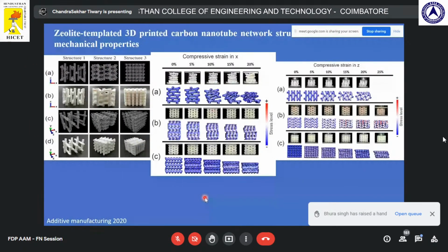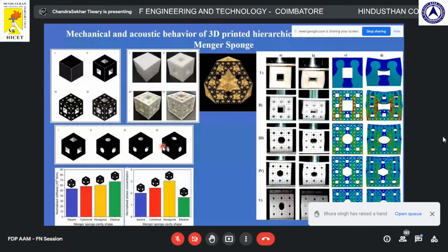Now we can also build more complicated structures which are inspired by nanoscale, which have topology, and some of these structures can give plastic or plastic-based material flexural strength, right? So you cannot really bend it easily. Most plastics, in any form you make them, have very poor flexural strength. We can introduce flexural strength, bending strength, and so on into the material, and the composite is what we have shown here. We can take a solid block and take out material selectively, and most of the structures are built by mathematical models. This is an example of a Menger sponge, where the scientist Menger built this structure with square porosity.